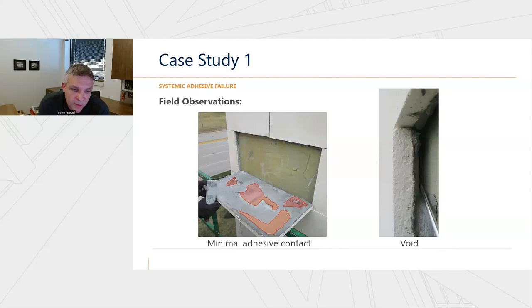The consequences of that are you clearly have reduced adhesive capacity because you've just got a smaller area where it is adhered. There's open joints in the system because it's a dry stack that allow water into the backup, and then that water can freely travel laterally within the backup, deteriorate the adhesive bond. And in a freeze-thaw climate like this, it can lens, so you get ice lensing where it forms subsequent layers of ice and eventually can push out on the units as well.